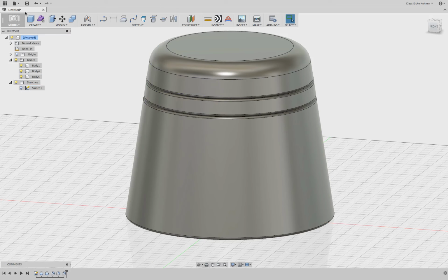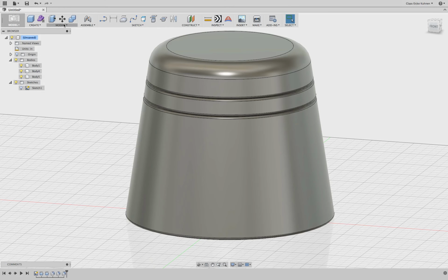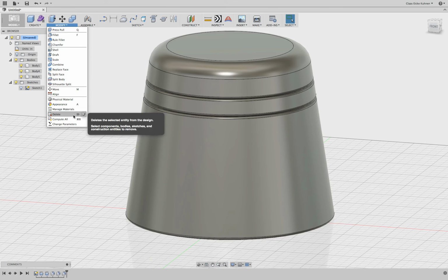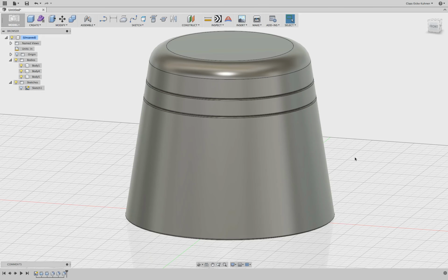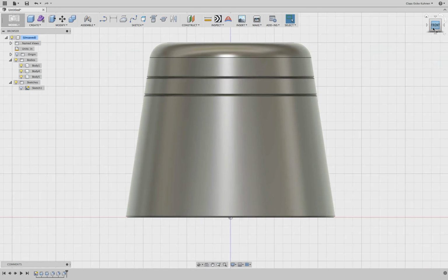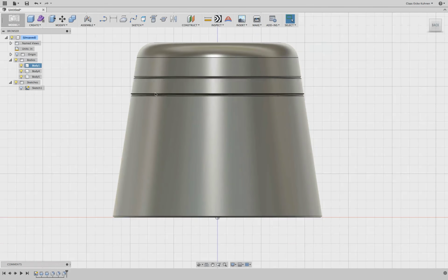And then again, let's do this as an exercise. We could go to change parameters. So where do we have D23? There. And let's say 1/8 of an inch. And there you see everything is updated. Pretty fantastic. And for woodwork, this is really way, way too much.